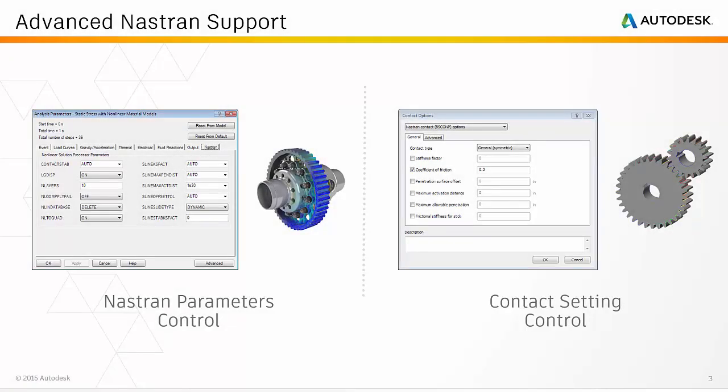As you may be well aware, back in Simulation Mechanical 2015, we introduced the Autodesk Nastran solvers and the Autodesk Nastran editor. This initial functionality covered several analysis types. In the 2016 release, we significantly expanded our Nastran capabilities. The 2016 release supported several new nonlinear material models, nonlinear loads, constraints applied to local coordinate systems, and incremental results for nonlinear analyses performed using the Nastran solvers.